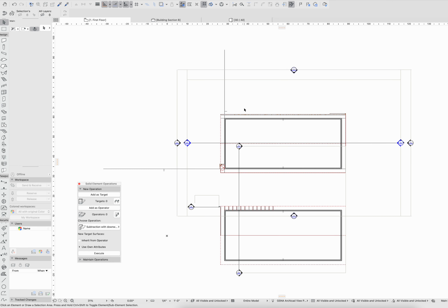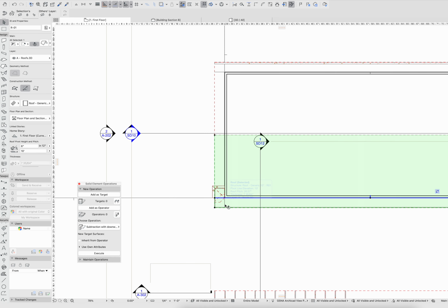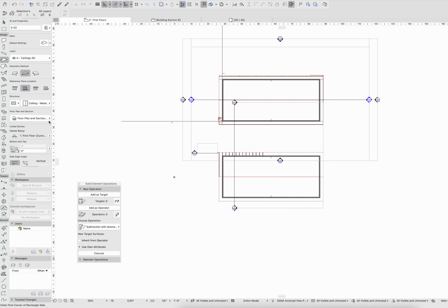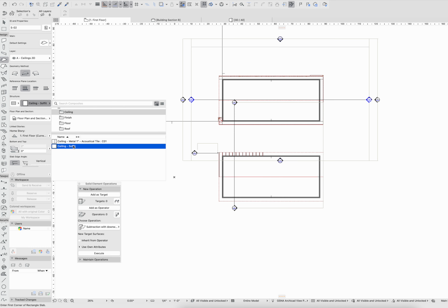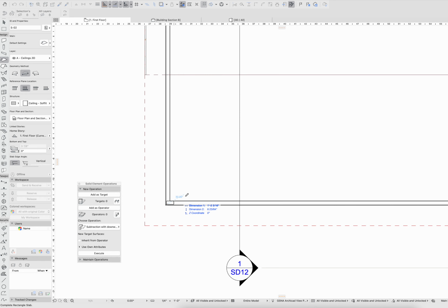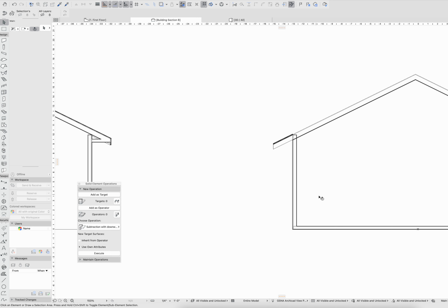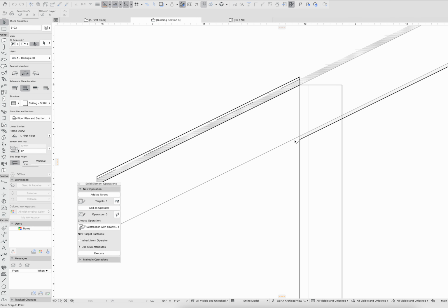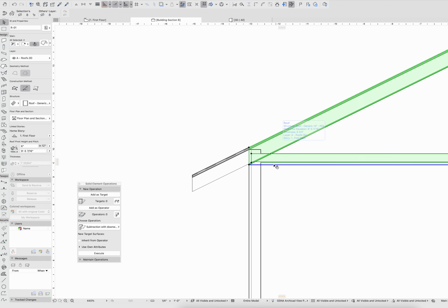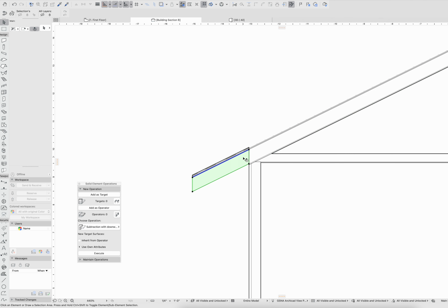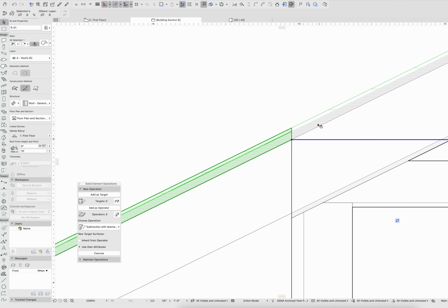If we come back into the floor plan, let's grab our soffit piece here again. That might be good enough for now. You might need a special composite for this as well, but let's go ahead and dump that in here. Now when we look at our section, right, this would be like the bottom chord of the truss, wherever that needs to come through. You can grab these things, right click, connect and merge. It should find the building materials where they need to exist. But then also we want to eliminate the overlap because this roof and this roof are overlapping each other.